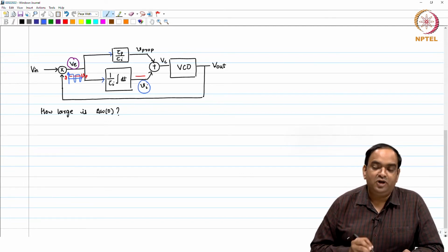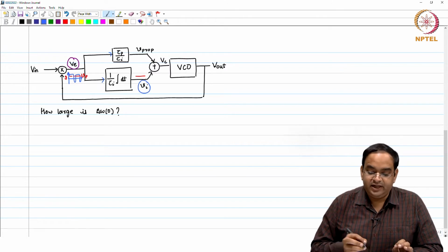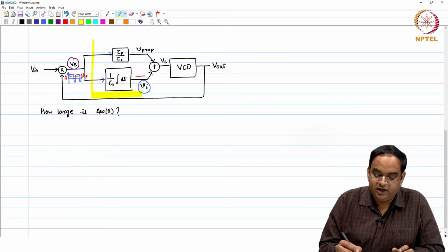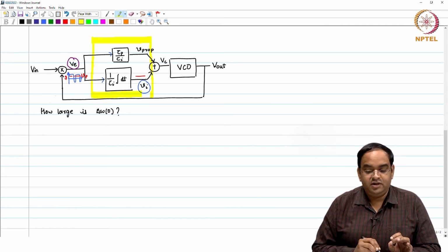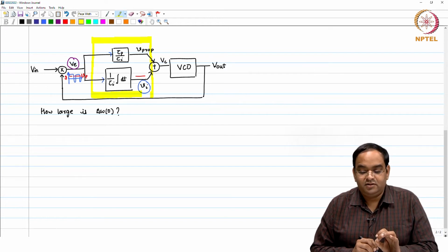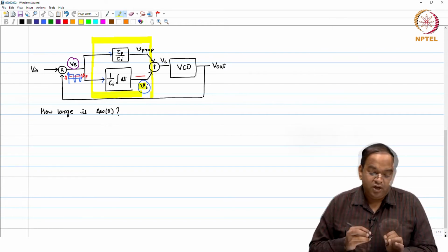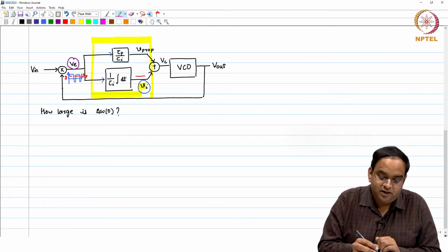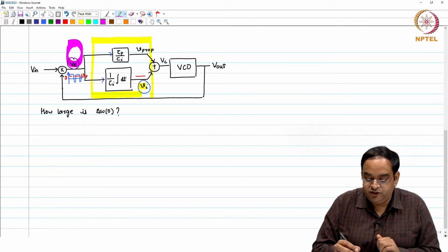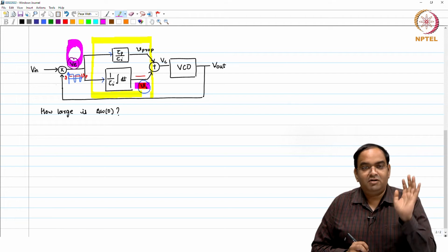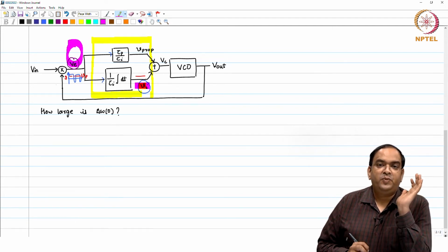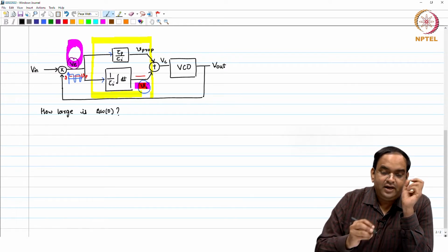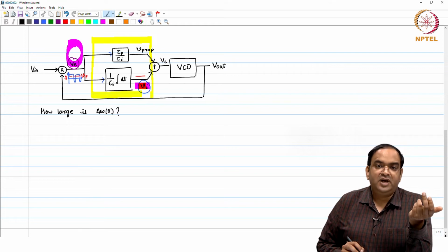So, it can generate any voltage, and in a steady state this loop filter can have any voltage which you want at your output without having a non-zero input voltage. So, having a 0 here and a non-zero Vi, whatever value you need, that is practical, you can always get it. If that is the case, then it does not matter what my initial frequency error is.